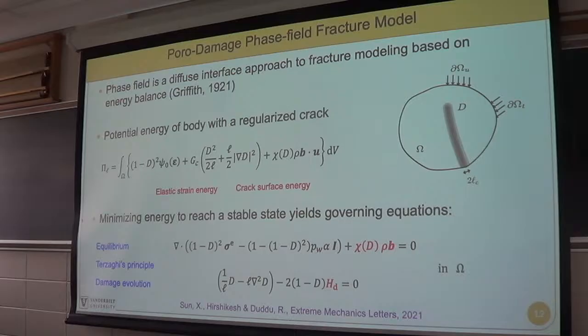But instead what you're saying is, let's call that a damage zone, and let's define an implicit function, a phase field function, which is a scalar function, that tells me that wherever that phase field is 1, let's say, that corresponds to the fracture, and wherever it's 0, that means it corresponds to the body, where there are no fractures, right? So by simply tracking the scalar value of this field at every point in the domain, I can say where the fracture is and where the fracture is not. So it's in a way sort of like a level set type approach, if that makes sense, right?